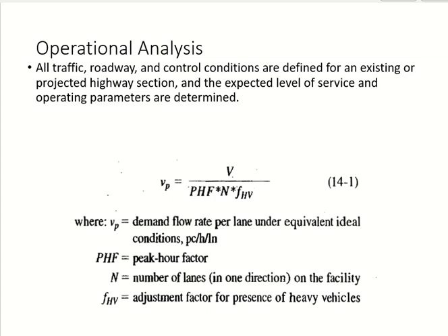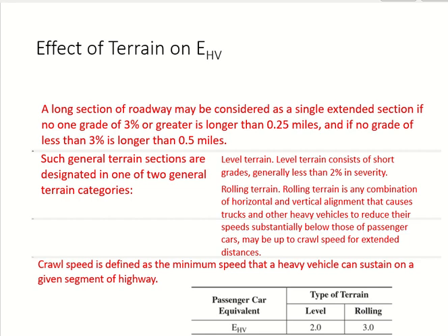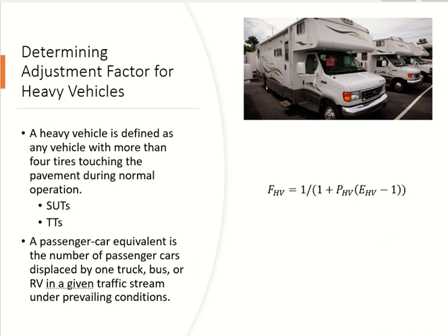Percentage of heavy vehicles. We want to calculate the heavy vehicle factor. Okay, let us do it. It's rolling terrain, so my EHV is 3. Percentage of trucks, for your convenience to put in the equation. So how much is the FHV?